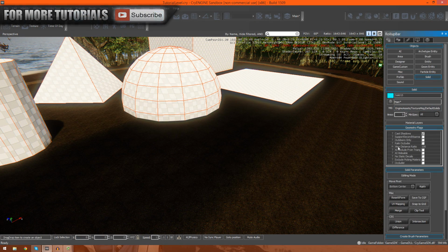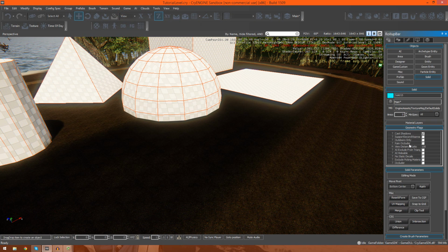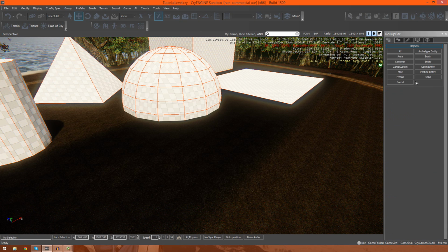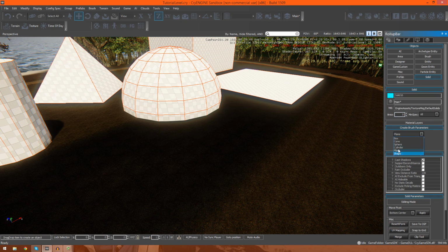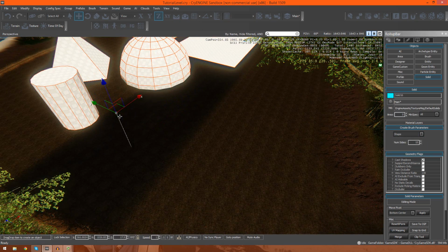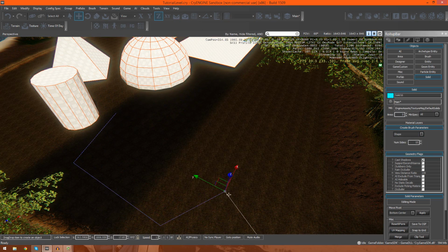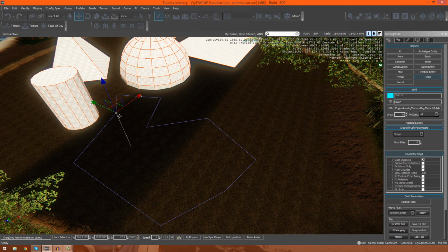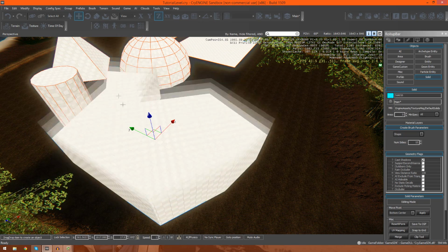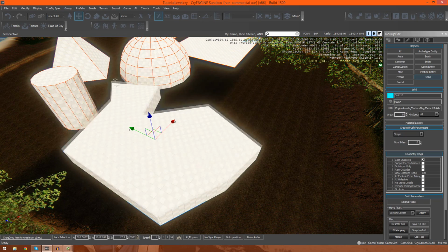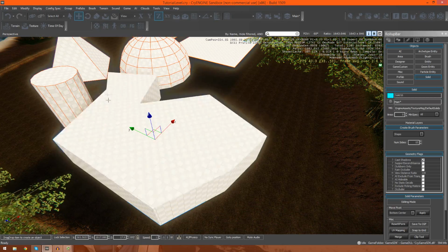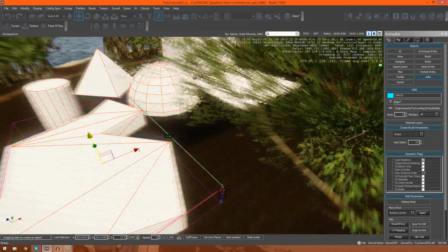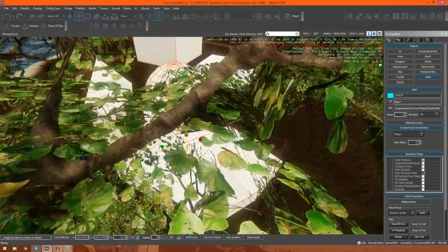The last thing on here out of the shapes that we can create is the shape tool, which allows you to create your own shapes in a pen tool kind of way. Let me show you that. If I select the shape tool and click once, I can then make a bunch of points which will make up a shape. I'm going to double click here, and then I can drag up and make that. When you get to that last point, just make sure that you have that little box there that you saw. So we now have a bunch of very basic shapes.